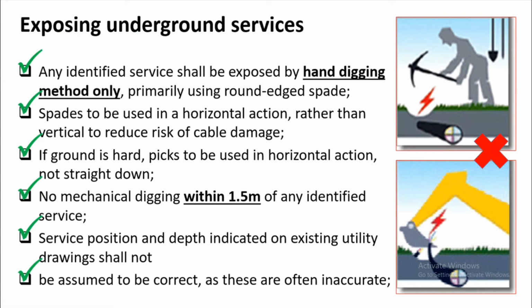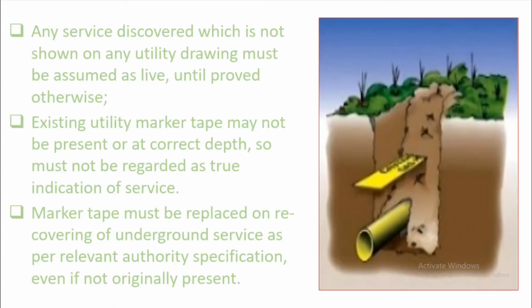So don't assume that the drawing and the dimension of the excavation, or the depth and position of the cable, is correct. Always treat this as inaccurate, so that you will avoid hitting the cable.